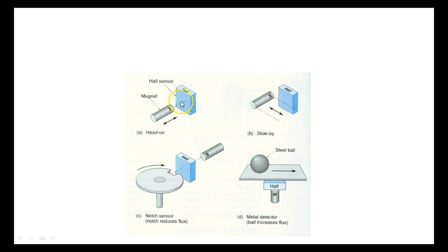This is what we were using it for, is we're just using it to sense when the magnetic field comes across it, right? You understand? And that's the way the cylinders are working. So we mount the Hall effect sensors out there, or we mount the magnetic sensors out there on the piston where we want to sense they are. If you notice, we can mount sensors all up and down those rails the way they're designed. So we could sense when it's like halfway, or we could sense quite a few things, right? You understand that?